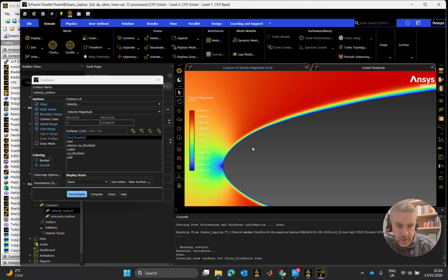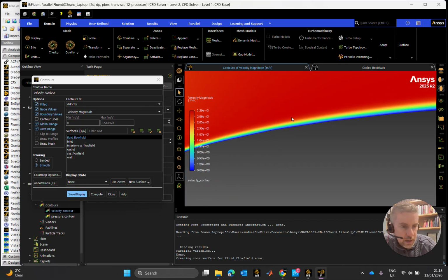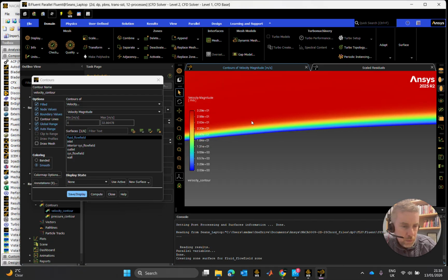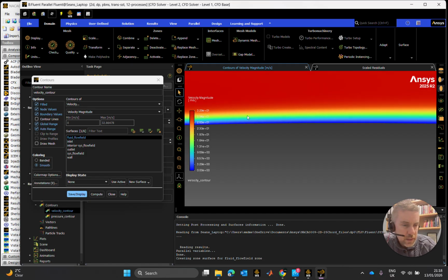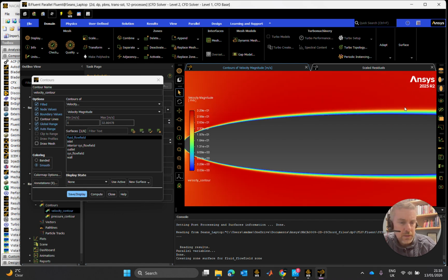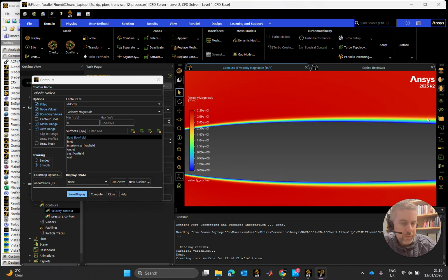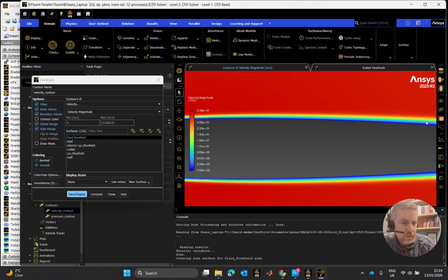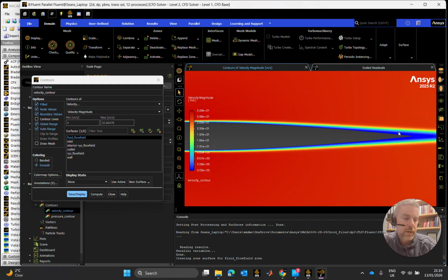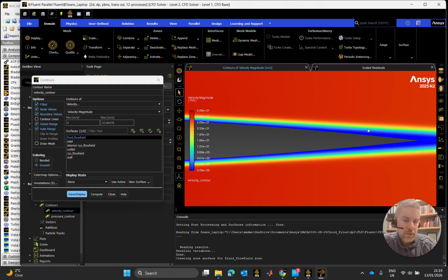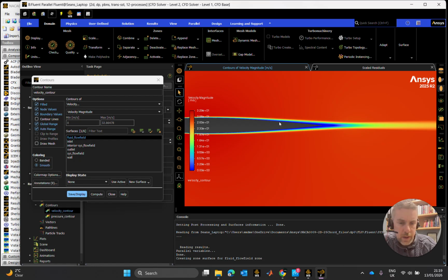It starts off very thin, and as we move to the back, you can see that kind of yellowy, orangey region gets more and more orange. Yellow gets thicker, sky blue gets thicker. That's the boundary layer. It's increasing. Right? So the longer that goes, the more friction you're getting, and the more the effect of the friction you get. And remarkably enough, on this NACA 0009 airfoil, it's sticking to the airfoil very well,